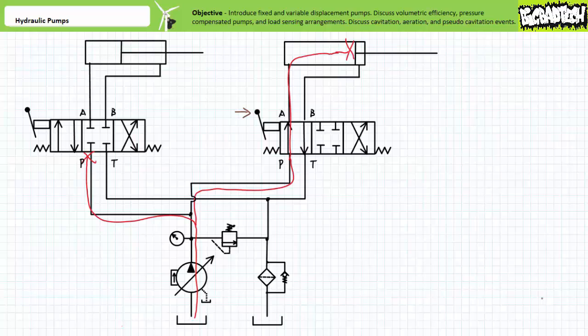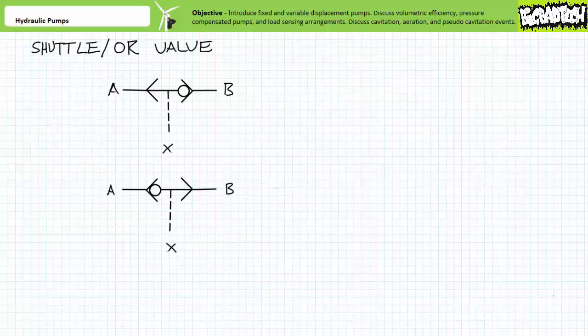Again, the advantage of this scenario provided by the pressure compensated variable displacement pump is that closed center valves can be used without the necessity of regularly actuating the main pressure relief valve, all the while allowing each actuator to operate independently of one another. Moving on, a closely related pumping scheme known as load sensing can be used to keep not only pressure, but flow rate constant inside a given range.